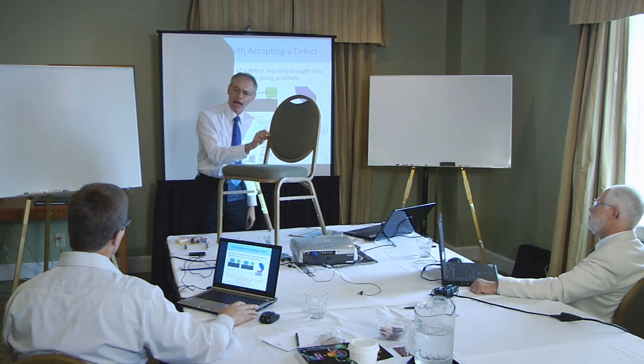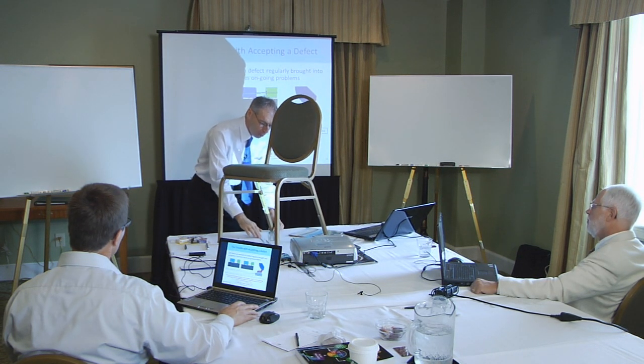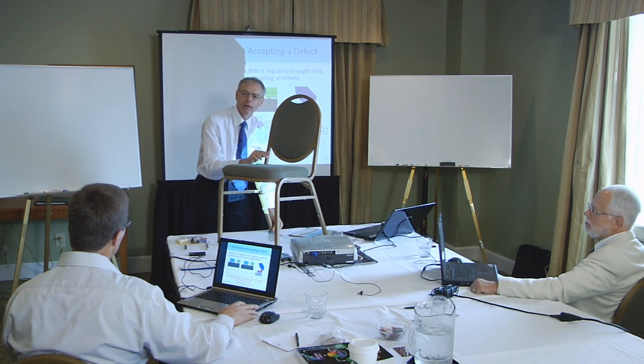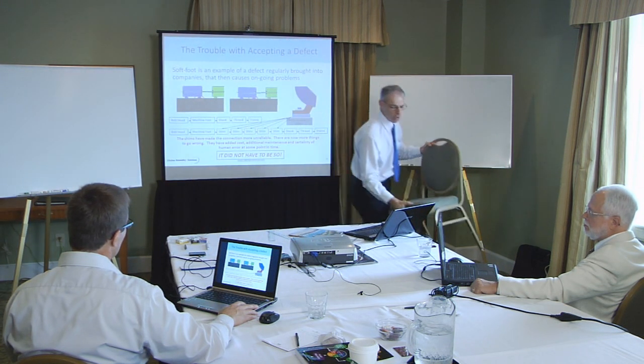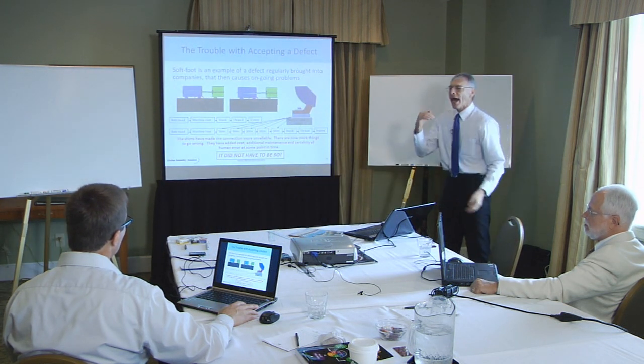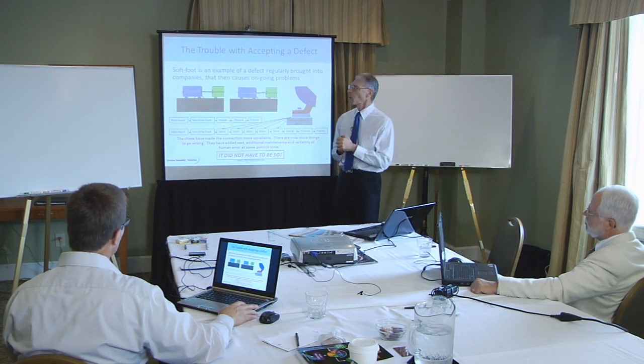So if I have soft foot, I can solve it. I solve soft foot by putting a shim there, problem gone away. So yeah, we can fix that problem. Soft foot is something that certainly is solvable. The hassle is we then give ourselves a reliability problem for the remaining life of this equipment.